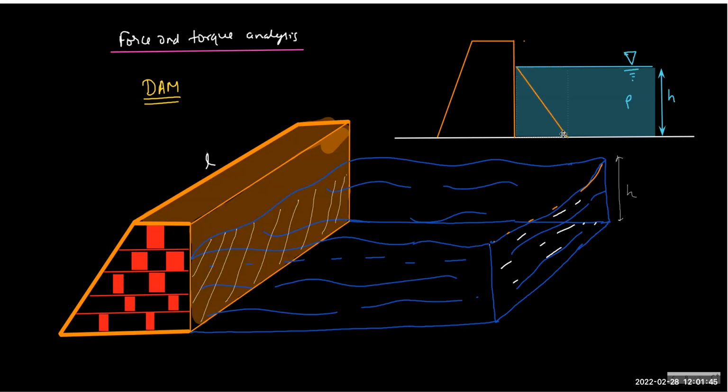What I'm representing is the pressure due to the liquid itself, not other pressure. We can draw a diagram like this. Pressure will grow in value as you go down, and the arrow represents the magnitude of pressure. As you go down, pressure grows, and we represent it by varying length. Since it is increasing proportionally, we can draw a straight line. So the length will grow proportional to the depth.